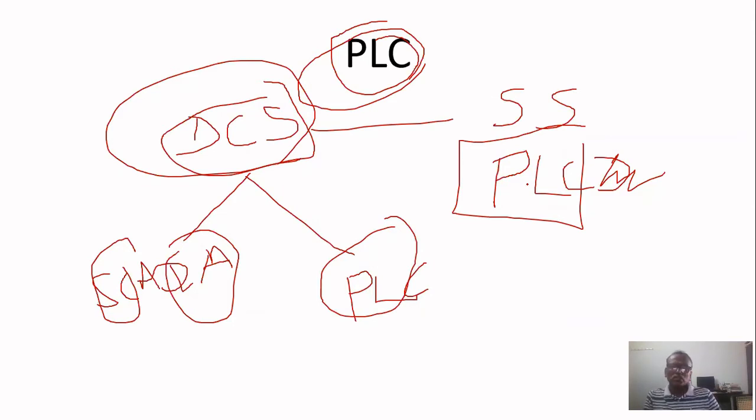Suppose you want to bring the process to 50% nominal operating point, it means you cannot open the valve directly to 50%. If you open it so, there will be large oscillation, and it won't come directly to 50%. You know that suppose a person is running a 100 meters race, then he will start from zero velocity, but he cannot end at zero velocity. So he will cross that line, and take some time to come to rest.